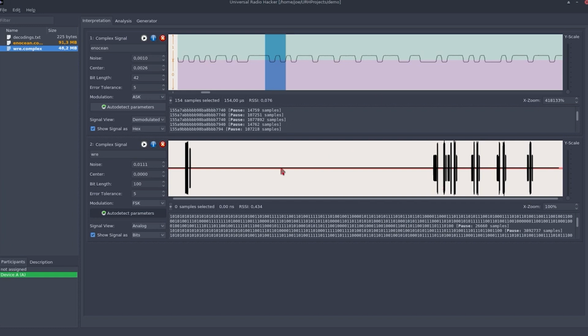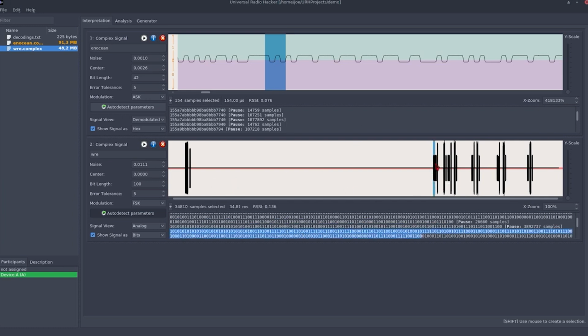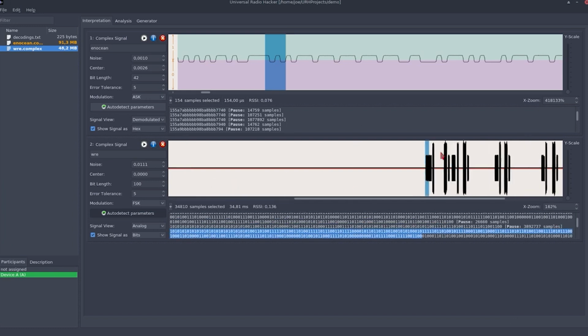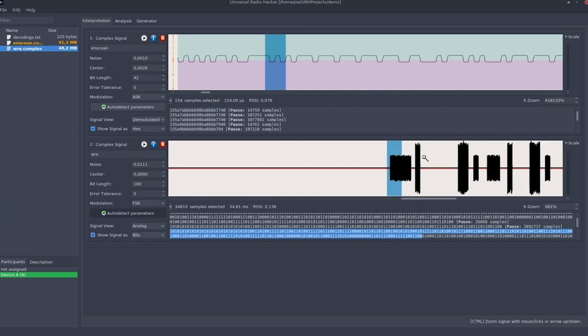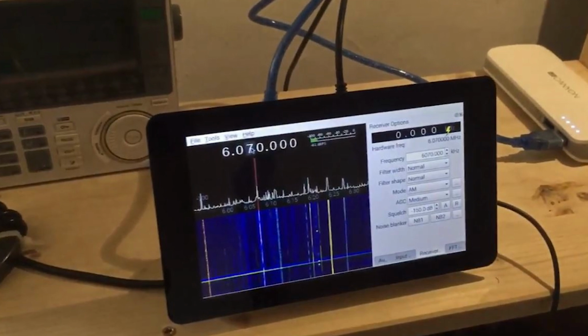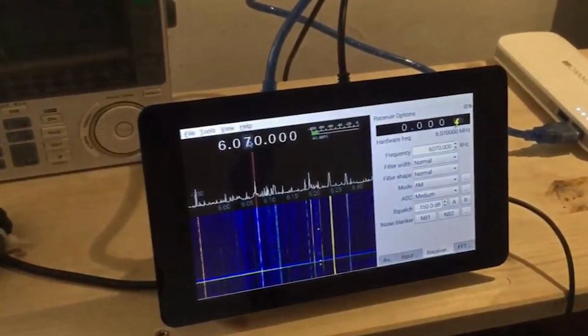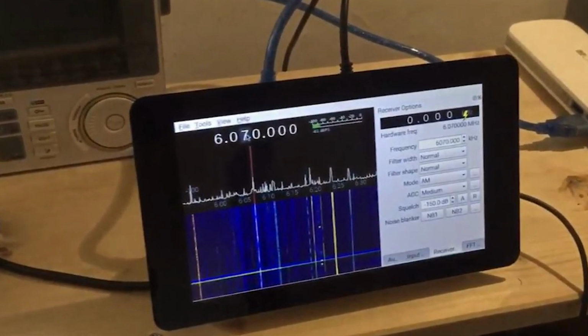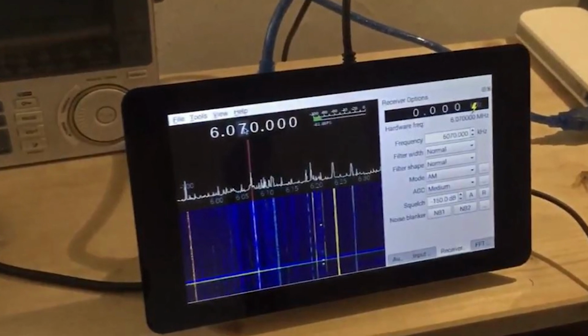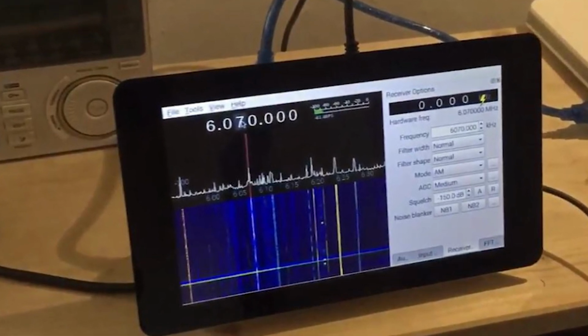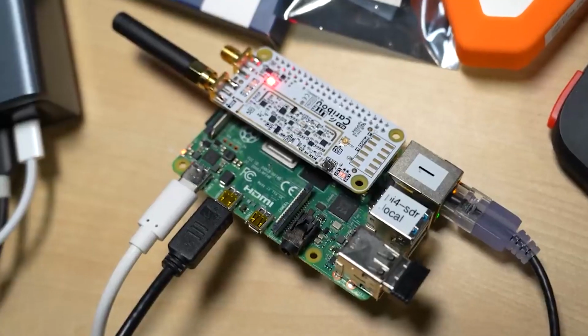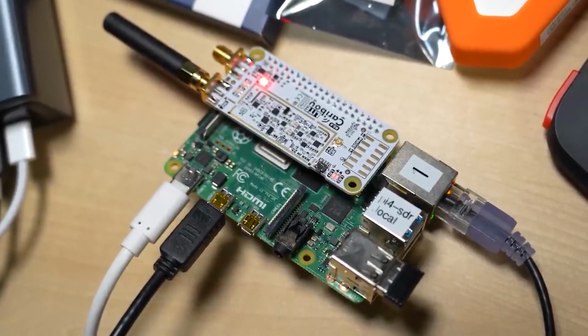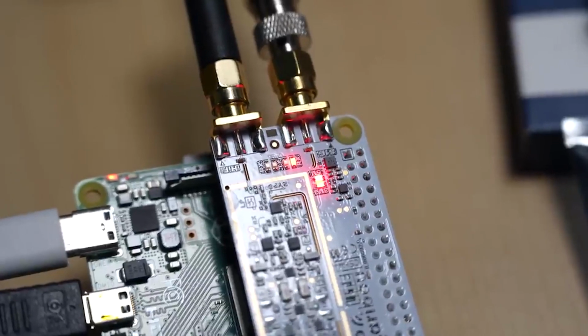Now the signal replay: you can use rpitx's sendiq command to transmit the captured signal. Ensure the transmission frequency matches the original signal. Now, there are some legal and ethical considerations that you're going to have to consider, right? Only perform replay attacks on devices you own or have explicit permission to test. Be aware that this technique may not work on modern vehicles with rolling code security.